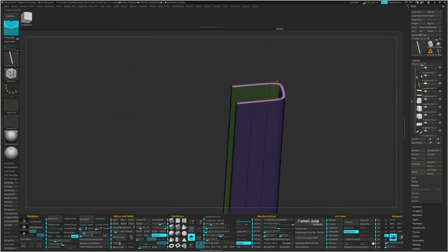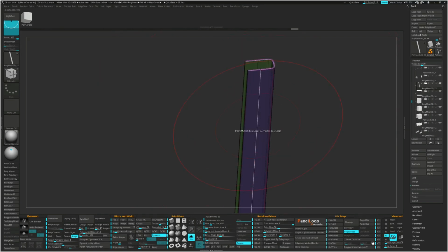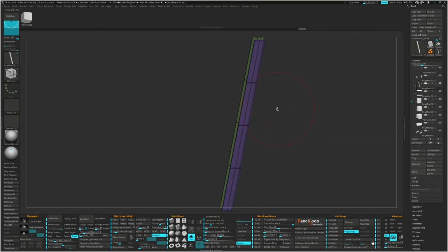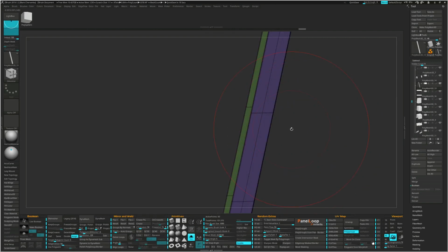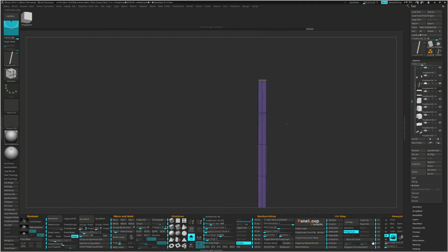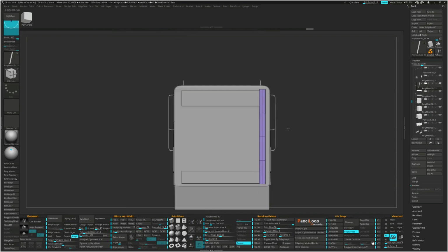Add an edge loop right down the middle and 3 of them running horizontally. Hover over a point and select Split. Looks like it might be a little too long. It's better to make that adjustment before punching in the holes.